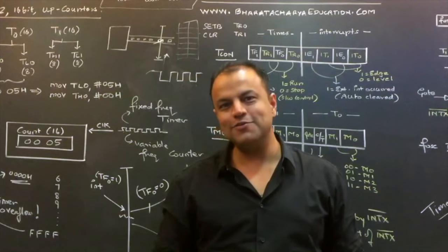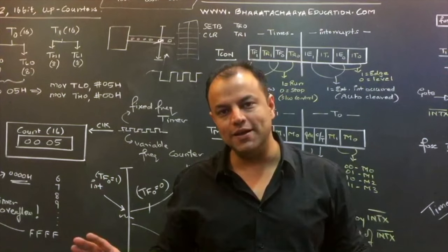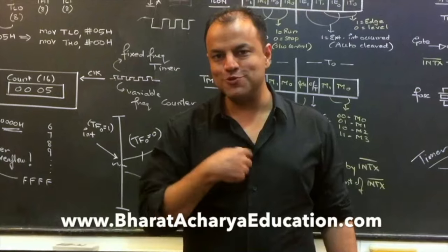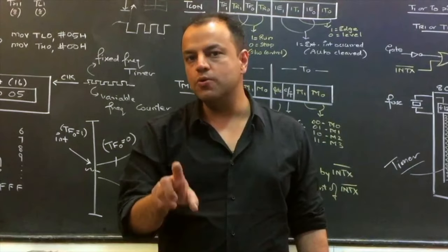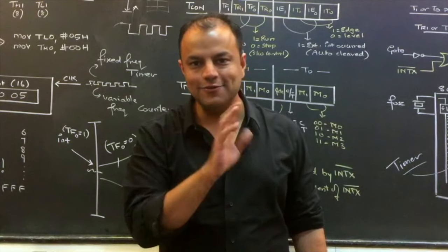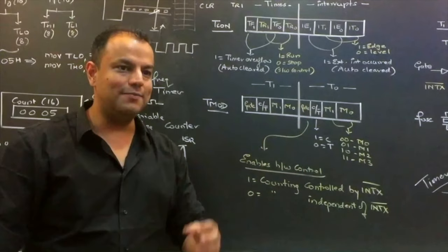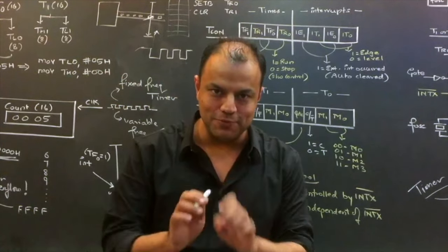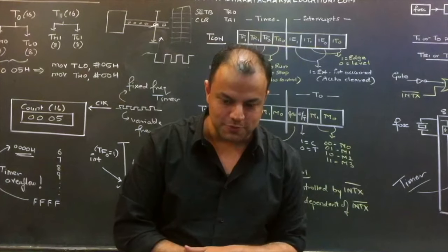When I started this video, the first thing I made you understand is this is a hardware delay. Processor tells the timer to count. Timer counts, processor is free to do other things. You have a dedicated hardware to do counting. So it is purely hardware delay. I didn't say it is software delay. What did I say? Software control. That means you start and stop the timer by instructions, by programming. Are you clear? Now why am I stressing so much on this point?